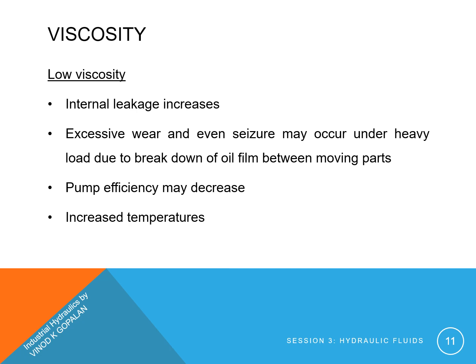Next, pump efficiency may decrease. If the internal leakage is more, that means obviously it will increase the volumetric loss, and because of that, pump efficiency may decrease. And fourth point is increased temperatures.